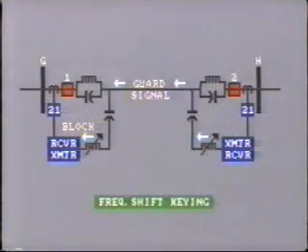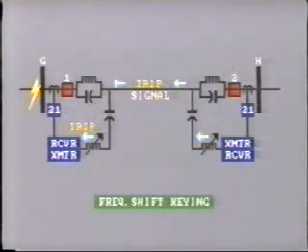Alternately, the signal can be sent by the FSK frequency shift method. Here, a guard signal is continuously transmitted at one particular frequency, and then, when action is required, the transmitter is keyed to change frequency. The receiver detects this change of frequency and initiates appropriate action. The FSK system is the preferred method nowadays, as it's more reliable due to the continuously monitored guard signal.